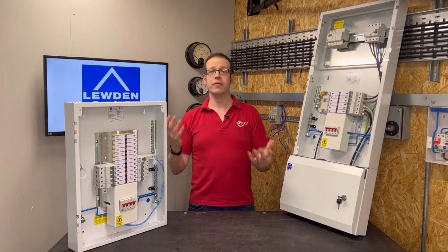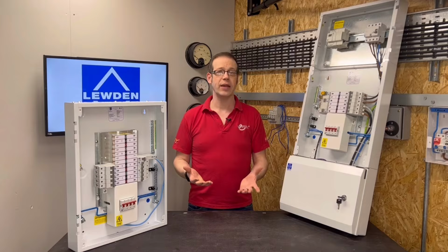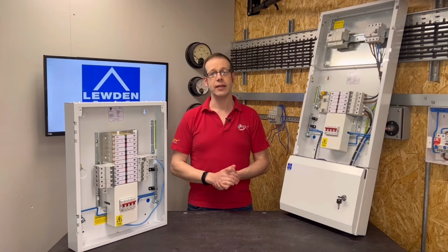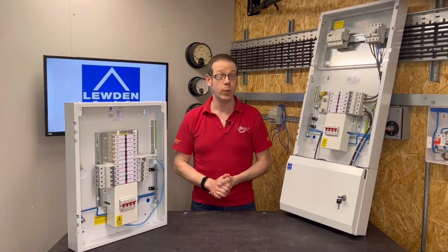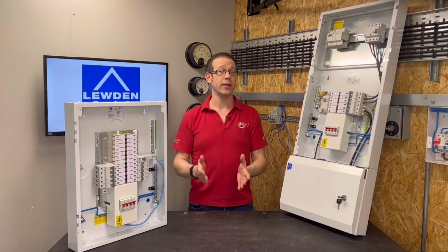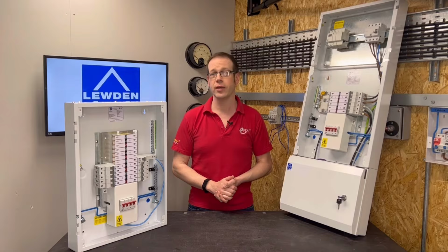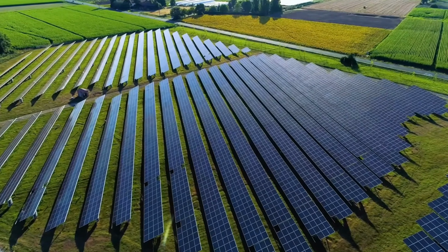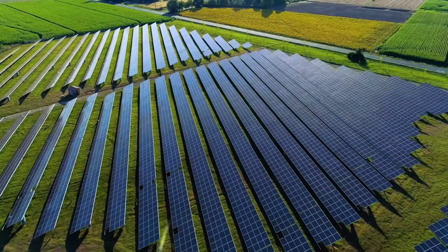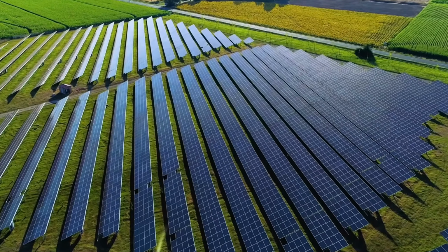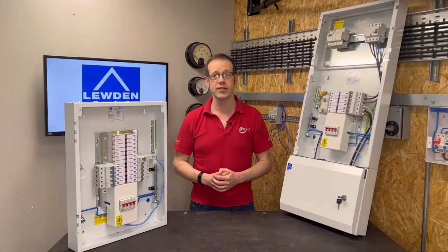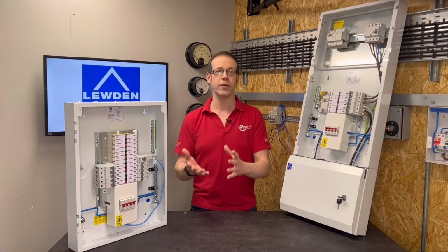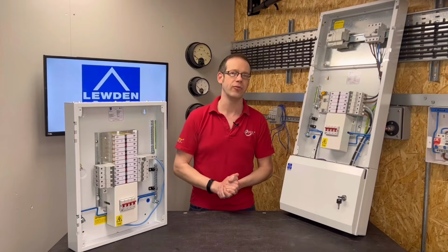Since then, there's been huge advances with modern electronics that has made stepping DC up and down easier and more efficient, making transmitting DC long distances much more efficient. We even use DC to connect countries together, like the high voltage DC connection between the UK and France. Indeed, with the rise of large-scale solar PV farms that generate DC and the increased efficiency in power electronics, it could be argued we'd be better off going to a DC transmission system rather than converting DC to AC to send long distances and then often converting back to DC for a lot of electronic loads.